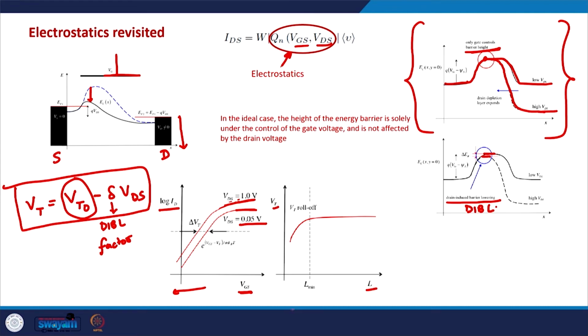What it shows is that the threshold voltage is ideally independent of the length for most of the lengths of the MOSFETs, but as soon as the device length starts getting smaller than a certain value, there is a reduction in the threshold voltage. So, the threshold voltage Vt becomes dependent on the channel length, and this is known as the threshold voltage roll off. One of the reasons of the roll off is DIBL.